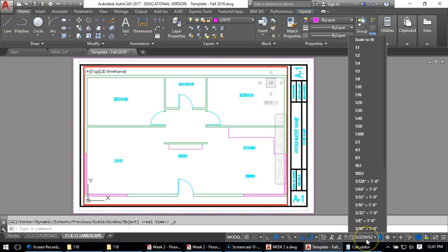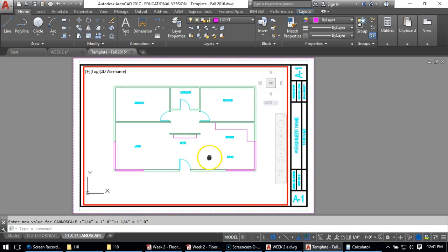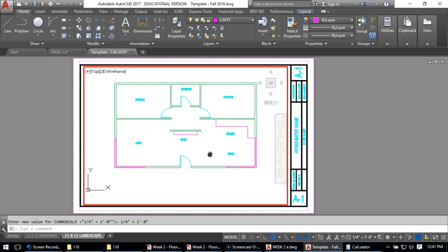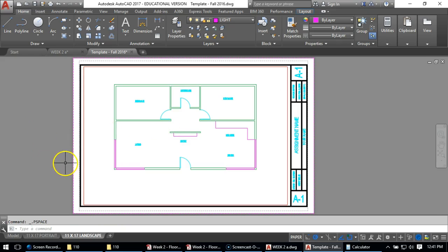So I'm going to go down to this location here, scroll down to 1/4 inch scale, and pan it sort of into place. I'm going to generally center it left to right, but since I'm going to add that title, I'm just going to slightly cheat it to the top side and double click out to enter off of it. And oh, actually, you know what? I just realized I forgot the deck as well, so I should put the deck in there.